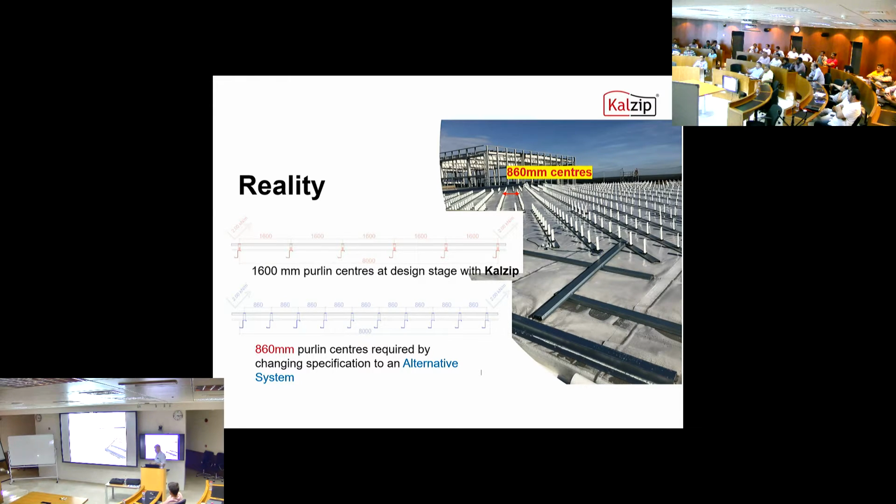And what is the difference between the vapour barrier if it's adhesive or normal? It's just the vapour resistivity. So the clear VCL reinforced will have better vapour resistivity performance. And sometimes the EPDM self-adhesive makes the lap detail a bit easier because it's already there, you just stick one onto the other. With this type of VCL you have to put butyl tape in as well. So it may be a bit more time on site.